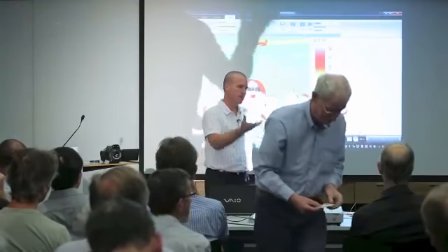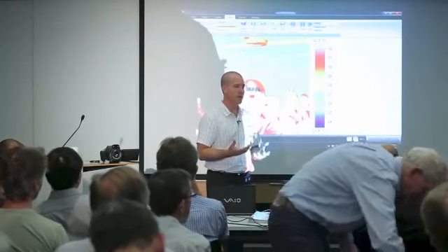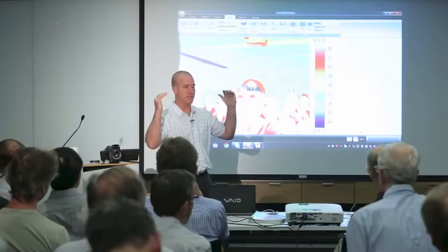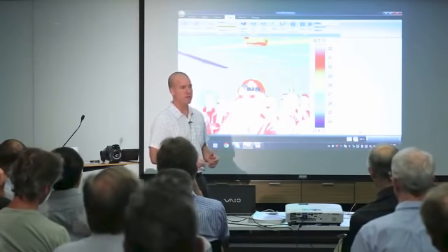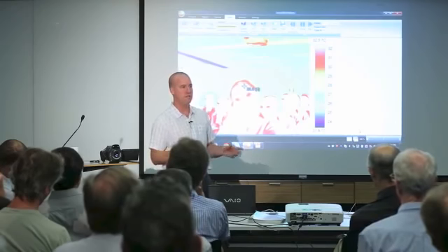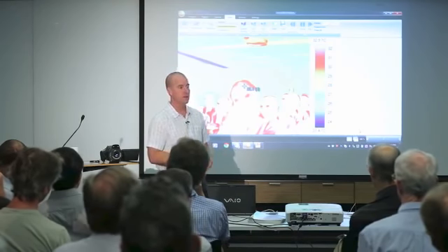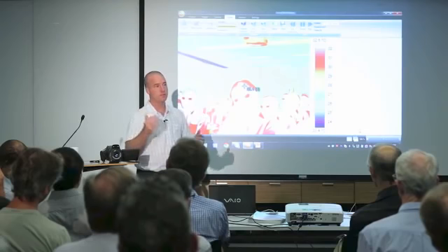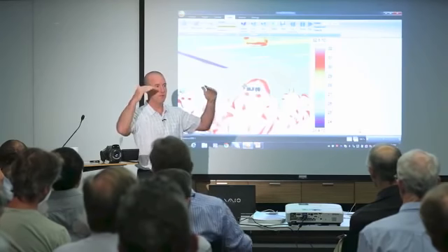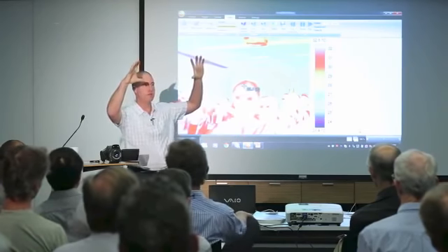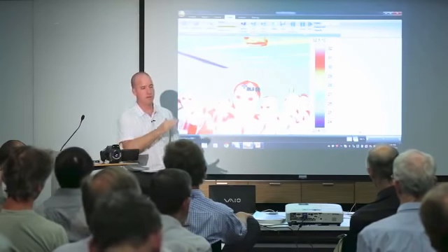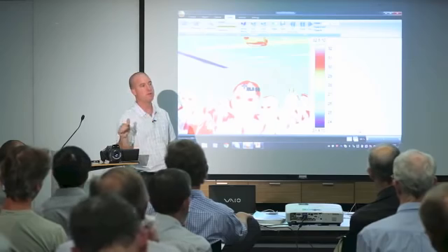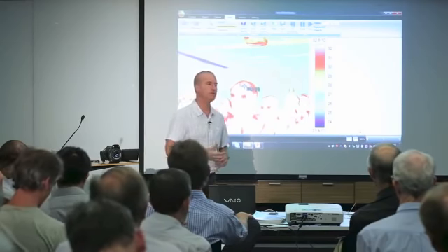Yeah, but the warmth will come upwards anyway. So what we find at our place is that if you close the curtains and the ceiling is charged, like we've got one of those Canara fireplaces, throw some logs in that, it warms us up while we're watching TV, we go to bed, the fire goes out, and we wake up in the morning and the house is still warm, because the curtains are drawn and the ceiling is warm and the insulation's above it. So there's nowhere for the heat to go. It just slowly passes through the insulation. So it's quite simple to keep your house at 19, 20 degrees by the time it gets to morning, just using a fireplace in the worst part of winter.